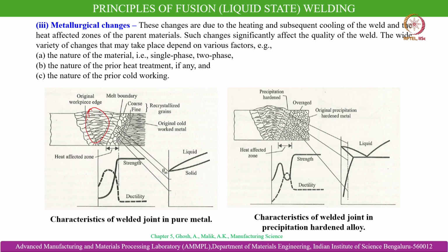This is the region of the melt pool, and this is the melt pool boundary. This is the region where rapid solidification takes place post melt pool formation. Beyond that there are some coarse grains, which are happening because of the heat that is generated in the weld zone. If we drop the lines from here, it will be clear.